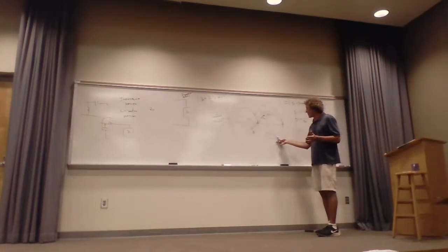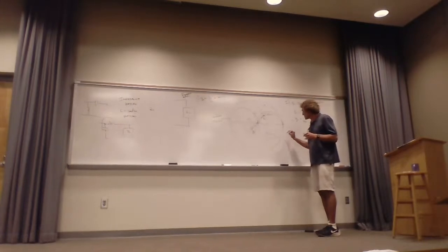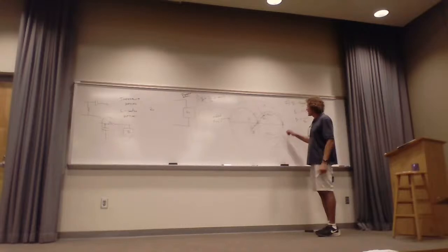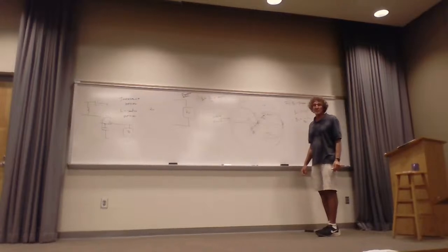And now I'll be on the 1 plus J something, right? Notice this, it's going to be 1 actually minus J something, isn't it? Because it's below the equator, right? 1 minus J something. So what do we add in series? Now we're in the impedance domain, an inductor. An inductor's impedance is J omega L, right? Now I'm going to do the whole 9 yards of this thing, but I want you to see the process. And again, this is how you go about it if the initial point is inside the 1 circle.